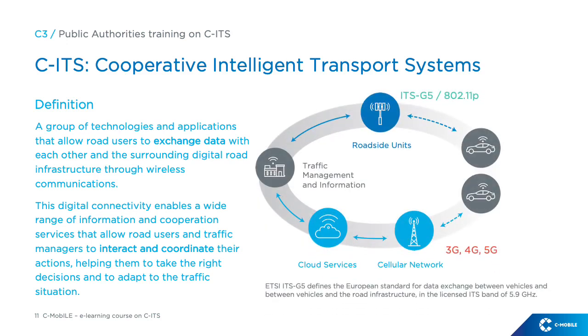Wireless communication technologies used in CITS can be classified into short-range, ETSI ITS G5 radio broadcast, which provides low latencies, useful for time-critical messages. Long-range, cellular networks, which provide wider coverage and scalable access to a large number of devices. These technologies complement each other and can be used together in a combined, hybrid way.